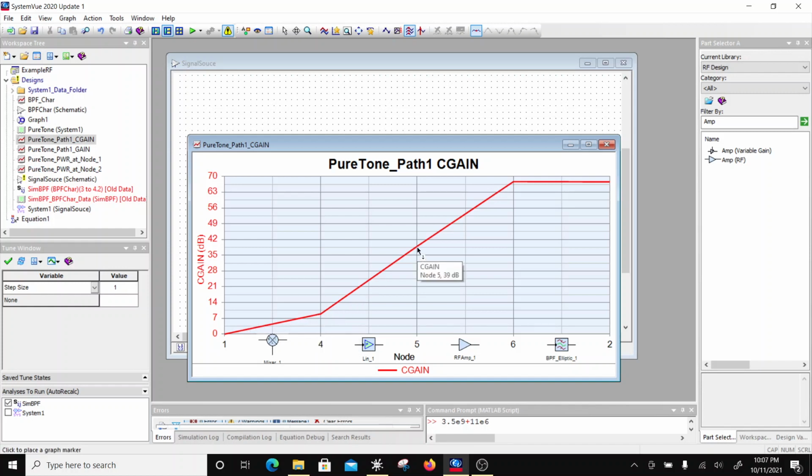And then there's nothing over here. So my 9 and 39. From 39 to 67.7. Instead of 69, I am getting 67.7. So that means that the PA is compressed by 2.3 dB. Right, so the PA is compressed by 2.3 dB, and then there will be no effect on the BPF.